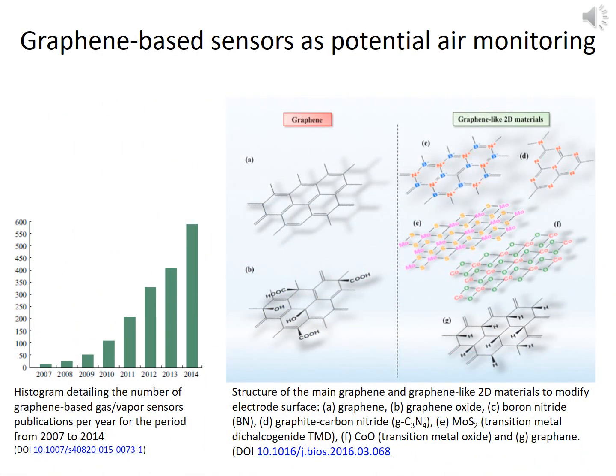Graphene has proved to be an excellent nanomaterial for application in gas and vapor sensors, due to its variety of structures, unique sensing performance, room temperature working conditions, and tremendous application prospects. Compared to other materials, graphene showed great potential for the construction of sensors, due to the combination of extraordinary properties such as the atomic thickness of graphene sheets, high carrier density, extremely high surface-to-volume ratio, and unique electrical properties such as high mobility and low electrical noise.